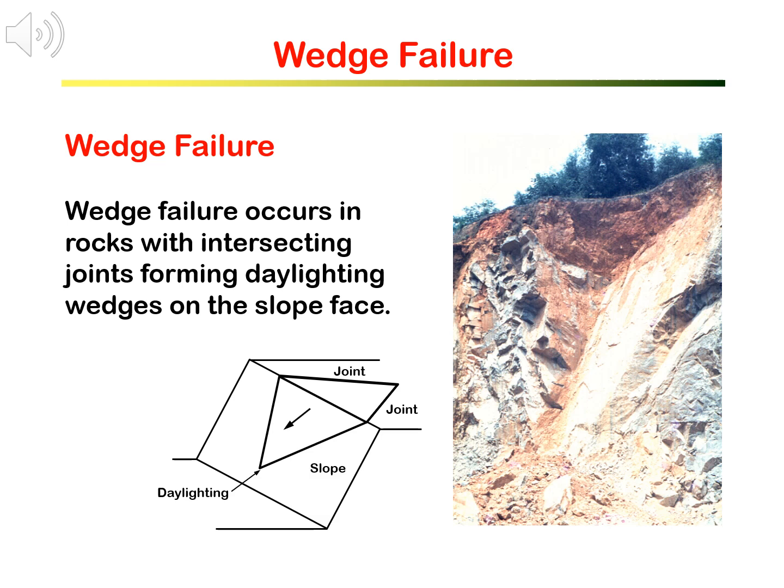One joint set is cutting into the slope from the right side, and you can see a large plane on the right side of the intersecting line. The other joint is cutting from the left, and you can see more parallel joints to the left. That wedge has slid and gone down the slope.